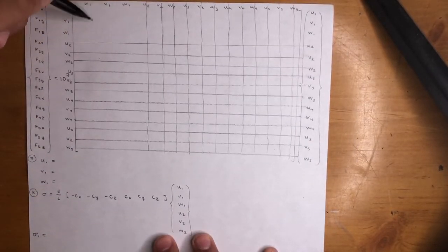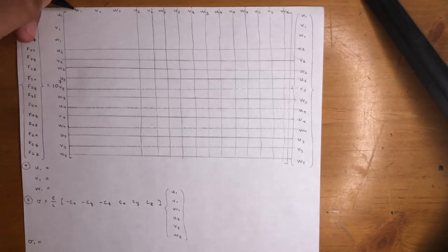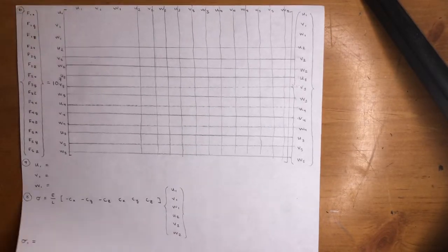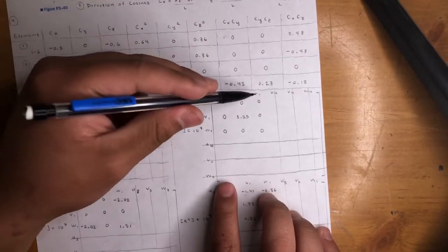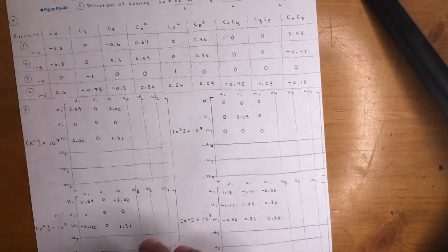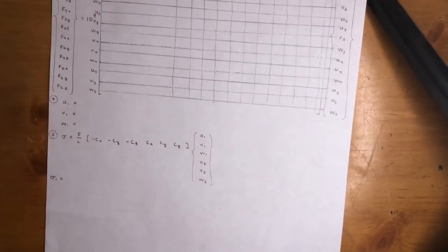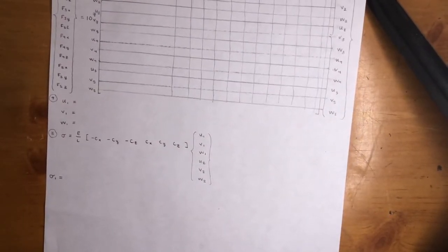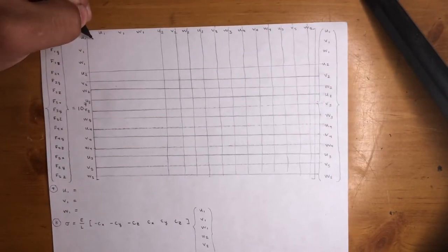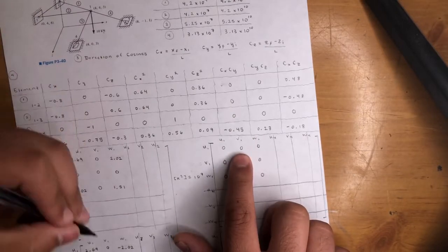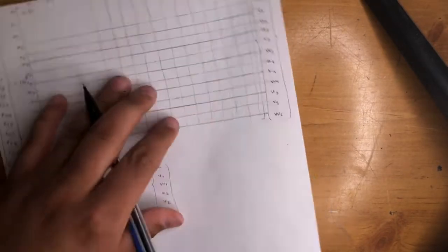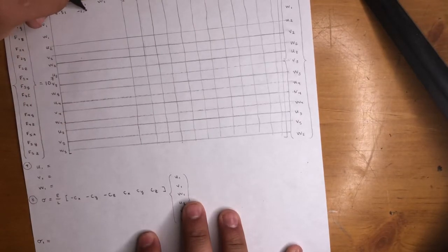So now we only focused on this 9 by 9 matrix, which lines up perfectly, right, with the other ones, U1, V1, W1, U1, V1, W1. So you add all the positions to each one, U1, V1, W1, U1 here, here, here, same thing. So 2.69 plus 2.69 plus 1.13 plus 0, that is going to give you, let me flip my other paper, 6.51 up here, okay? Do the next one, right? 0, 0, 0, negative 1.41. That is negative 1.41. And I'm gonna go ahead and do the rest for the remaining ones, right?